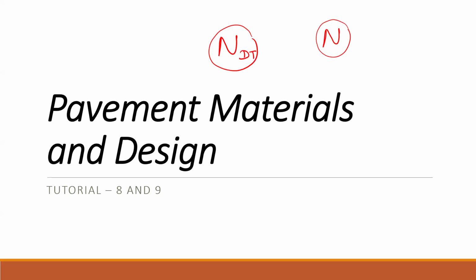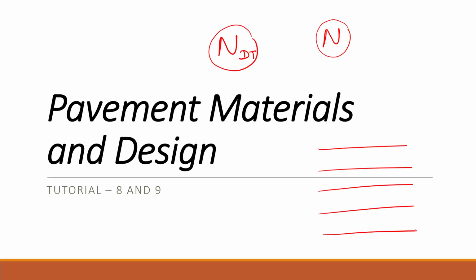So in pavement design, we start with a trial pavement. We have to decide which trial pavement we want to go ahead with. That means we select our materials, maybe 2 asphalt layers, and also a cemented layer, or maybe a granular layer, and the subgrade. So we start with a trial pavement, and we give our own thicknesses for the trial pavement, and we are finding out when we put this design traffic whether these pavement layers will be okay or not. So we are going to find out the allowable traffic for these different pavement layers.